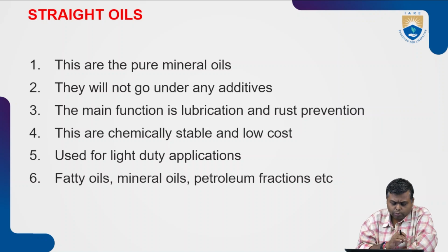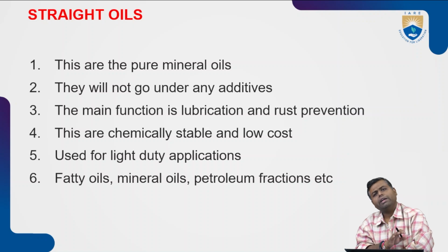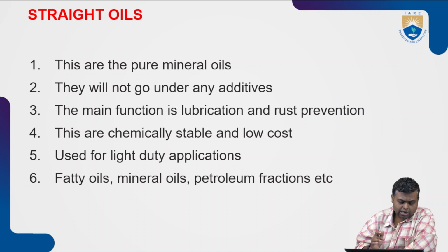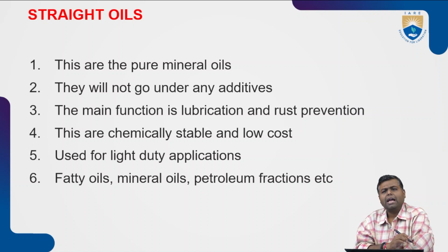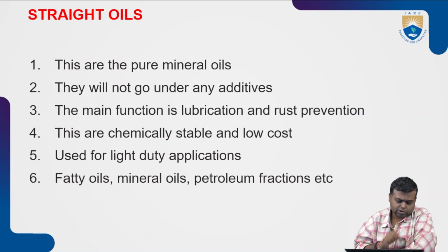Next, it should be chemically stable. Generally, the straight oils are chemically stable, and in some places where these straight oils are available in abundance, they are very low in cost. Next, you can use it for light duty application. Light duty means where the cutting speed, feed and depth of cut are minimal. There we can use it.